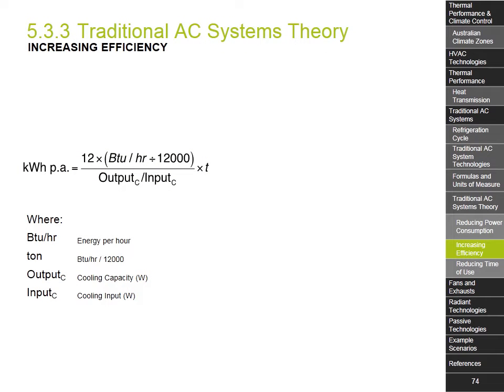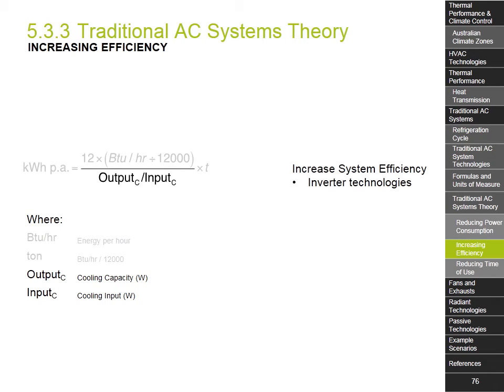Energy efficiency can also result from an increase in the efficiency of a system. Let's isolate the elements that relate to efficiency, which in this instance is the energy efficiency ratio, or EER. The required electrical input power and capacity of a unit is generally predetermined by all other efficiencies and power requirements. That is to say that the requirements and parameters of the room being conditioned are determined as a priority, and then a unit size is selected to deliver to that value.